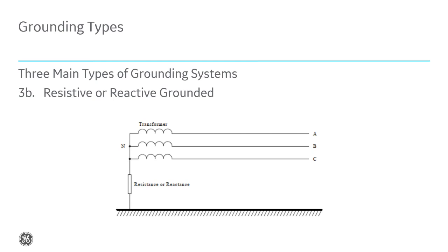Again, the disadvantage of it is, like the ungrounded and the Peterson coil grounded, it does change the neutral point of the system. And for phase to ground faults, the other phases, the unfaulted phases, are elevated in voltage, so insulation design needs to be taken into account, some more robust insulation design.